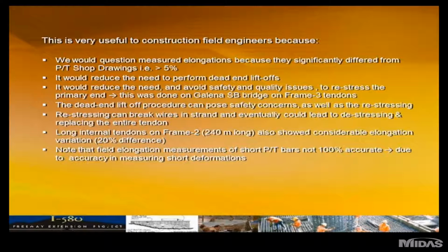And the reason why we did was because a single center of gravity profile was used, and some of our elongations varied up to 20% from the theoretical. So as you can see, it was a huge difference. These tendons are 240 meters long. They're draped in several spots with a very unique profile.